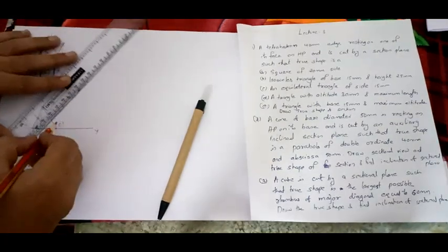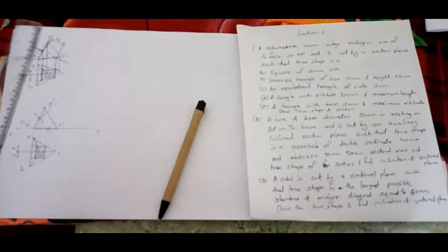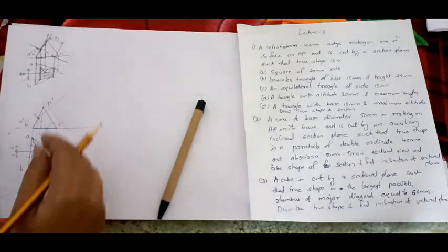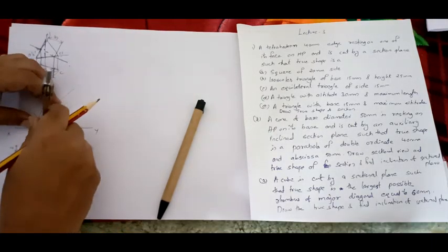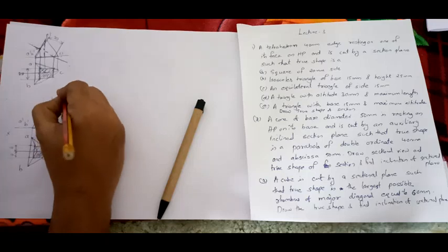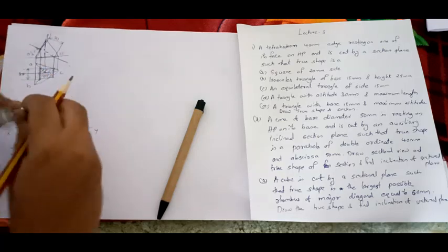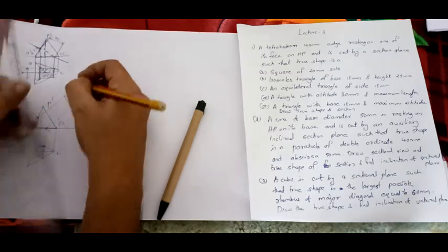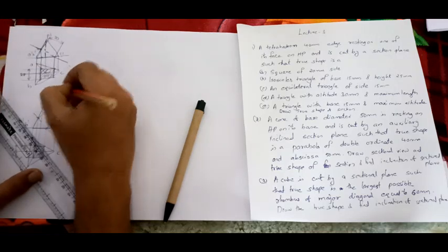Now to obtain the true shape, what you have to do is draw perpendicular lines from here. Now draw a line parallel to this line away from here. Now take this distance, take this distance 1. These two distances will usually be the same. So take this distance, cut it here. So you will get two points here. Similarly take this distance also. This distance and this distance will be the same. So you will get a square like this. See, I will complete that. This will be the true shape.